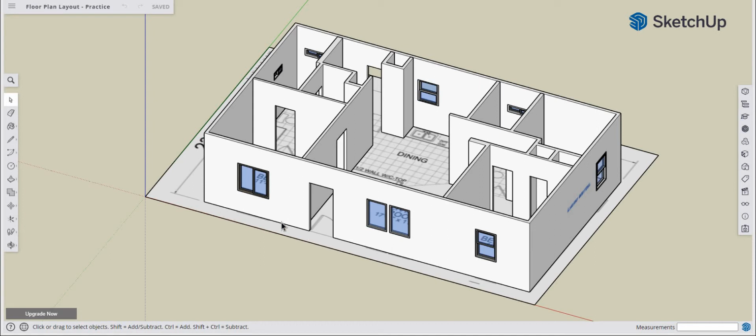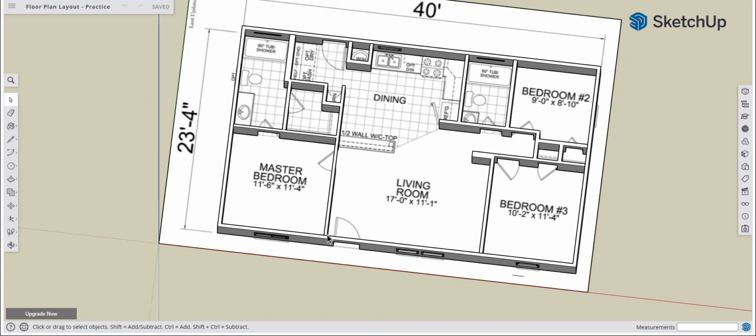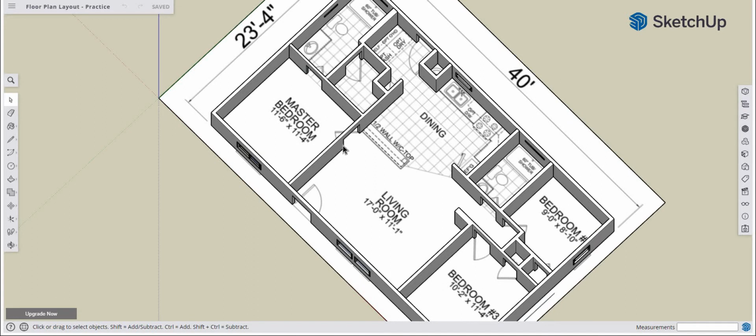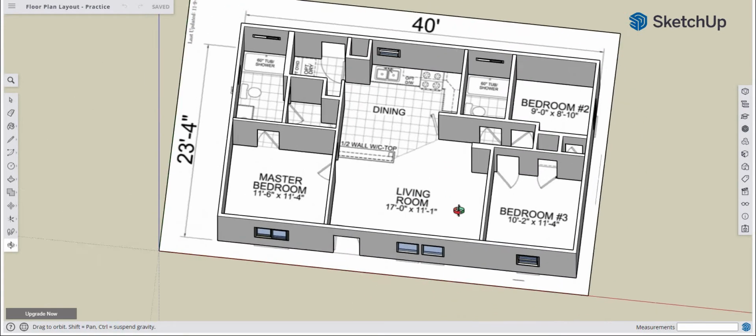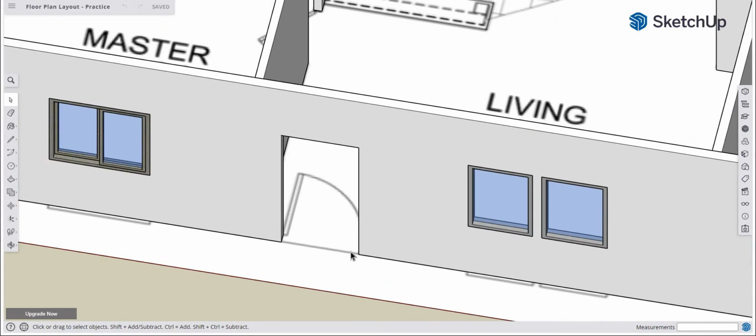All right, we're going to put some doors in this. There are actually 10 doorways in this entire thing, and we're going to put the same door in every single one. There will just be some adjustments, because if you notice, this door opens inside on the left hinge, and this one, if we swivel this guy around, opens inside on the right hinge. So we need to make some adjustments for a right and a left door.